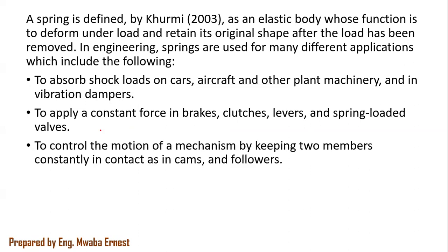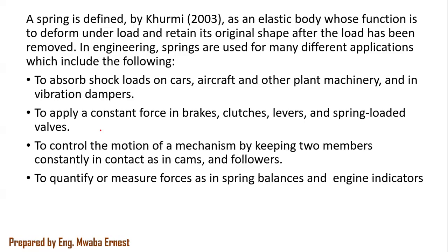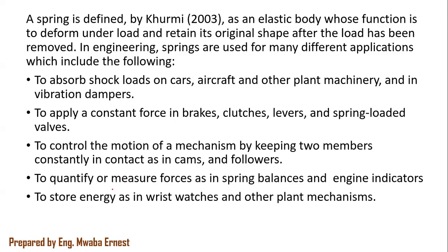In some other cases, we use the same springs for controlling motion, keeping members constantly engaged, like in cams and follower mechanisms, and many others. And if you talk about spring balances and engine indicators, these are there to measure forces. They also utilize a spring. If you've also heard about a strain gauge, which we use for the same purpose, where we could be trying to look at how much force is here, where we are applying Hooke's law, it also uses a spring. So all those are just used for that.